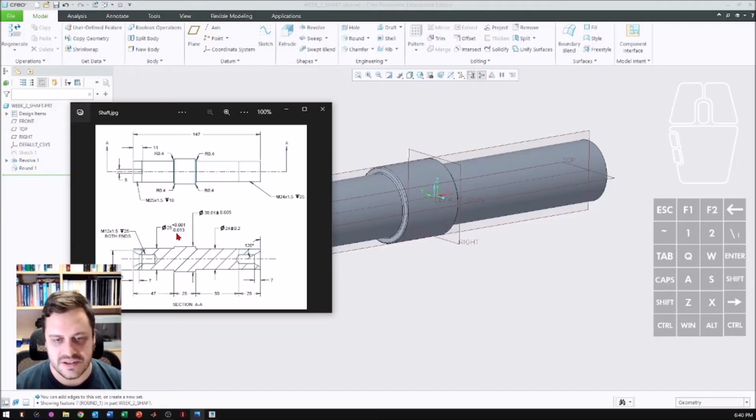So we've got most of the nuts and bolts here of this particular item. The only other thing I wanted to outline in this particular video was these bolt sections, if you like. What we're going to do is use the hole tool to effectively make these threaded sections that a bolt would go into.